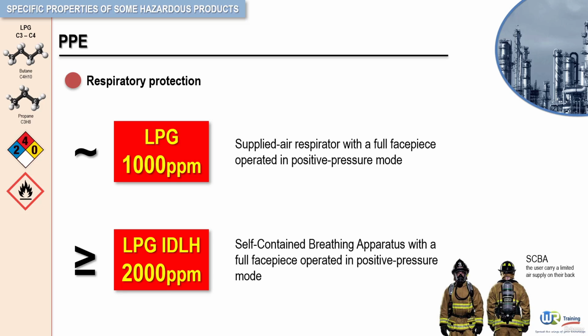Remember, exposure to liquefied petroleum gas is dangerous because it can replace oxygen and lead to suffocation. Only an approved self-contained breathing apparatus with a full face piece operated in the positive pressure mode should be used in oxygen-deficient environments.